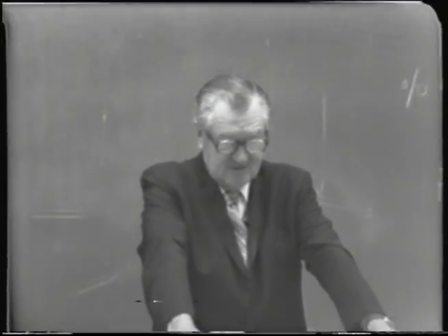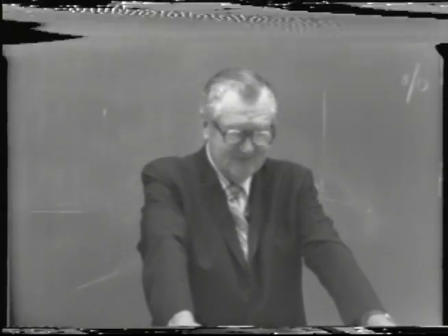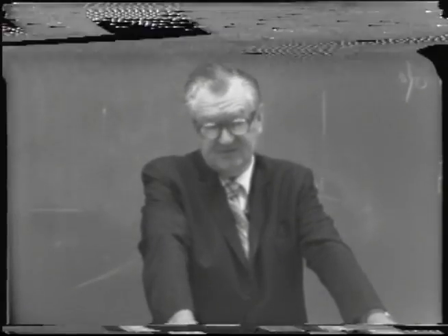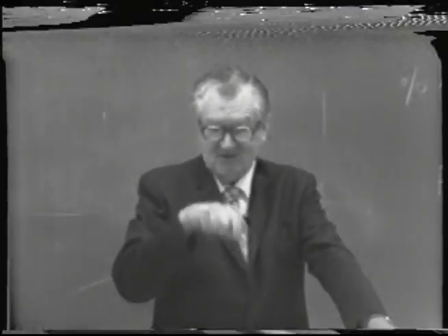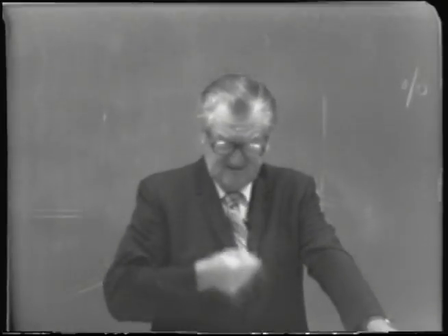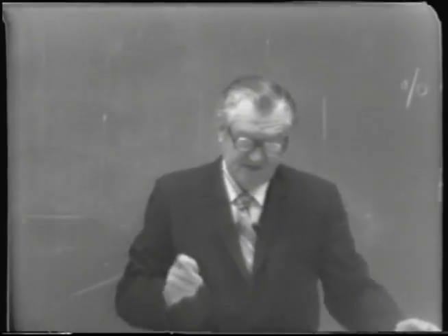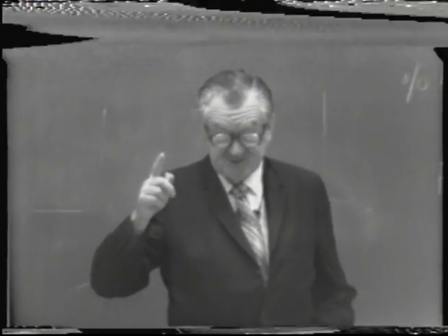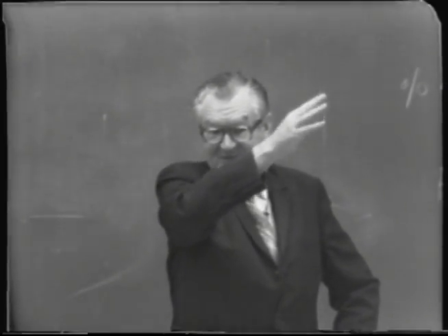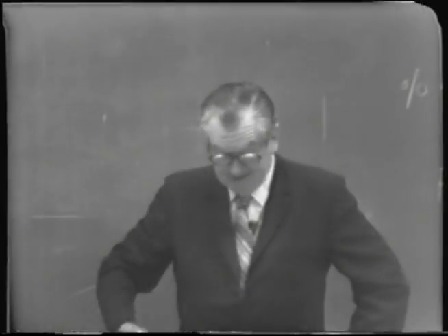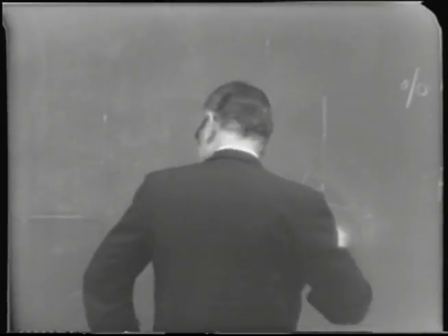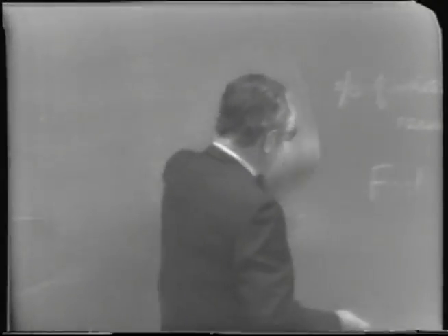Of course, if you split the columns, now we do call that a split column arrangement, where the distilling unit consists of a stripping column and a concentrating column. Naturally, you have to make some provision for connecting the vapor from the top of the stripping section to the bottom of the rectifying section. Maybe I might as well indicate what I'm talking about by a little sketch.